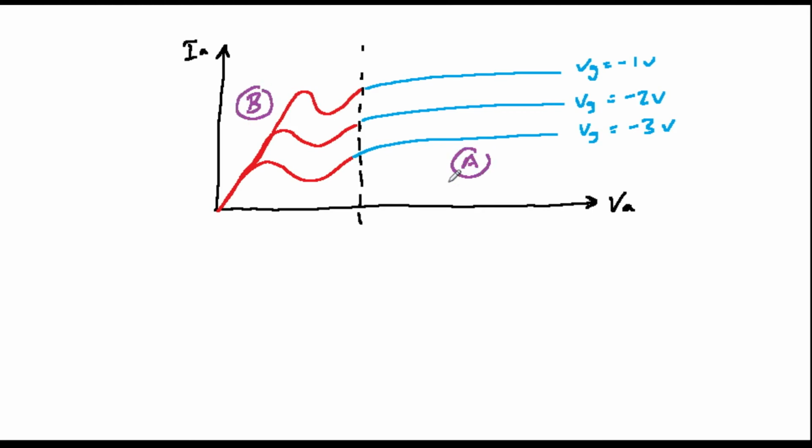An interesting thing about this kink region is that as the voltage increases, the current goes down. This is called a region of negative resistance, and it can cause instability and oscillation within the circuit. This is a major problem with tetrodes.